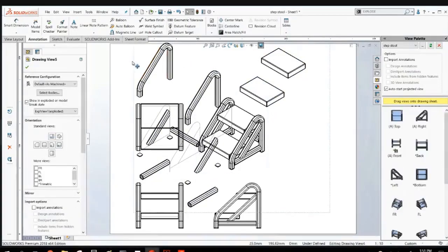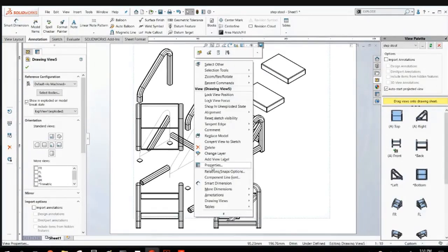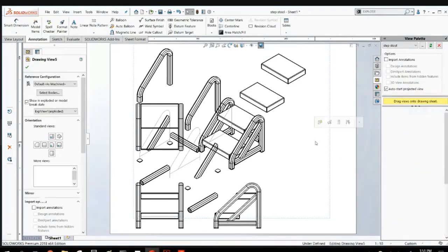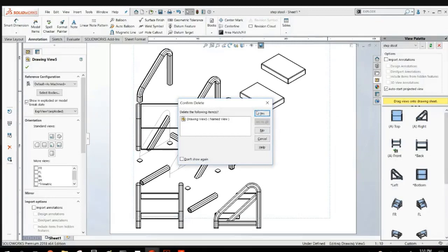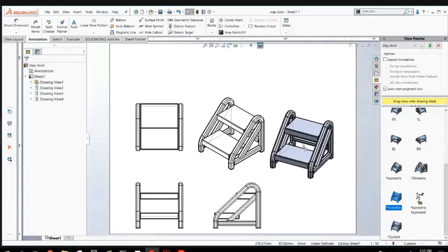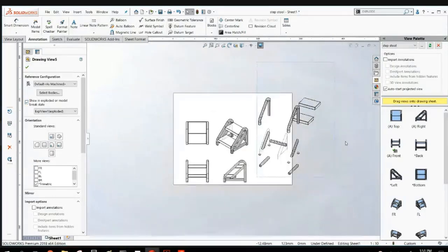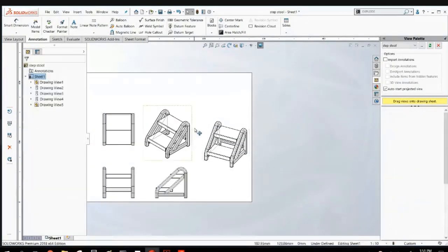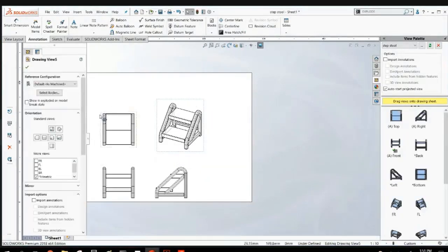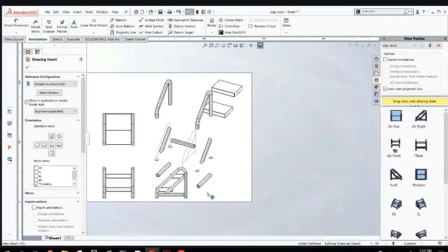you can drag and drop it just like you drag and drop an exploded view in an assembly, where either you can use the isometric exploded view, which will come in as a choice for you, or you can bring in any view, go over here, tell it to show it in exploded state or not. But you do need to do that at the model level first. Maybe we'll explode this view here, get it onto my page.